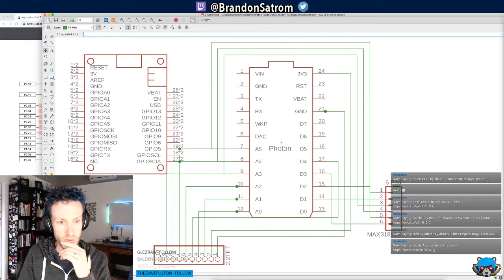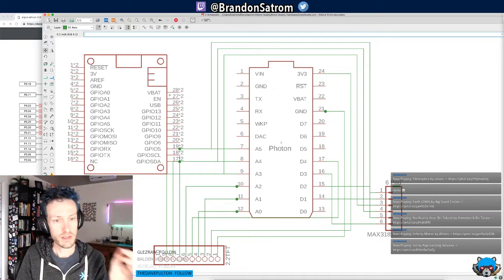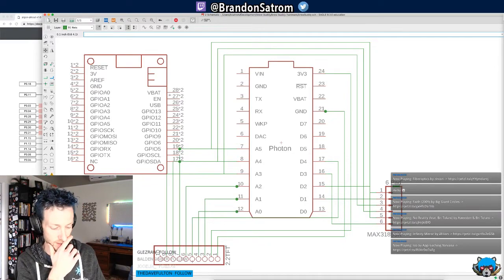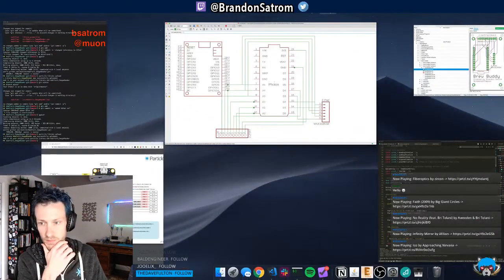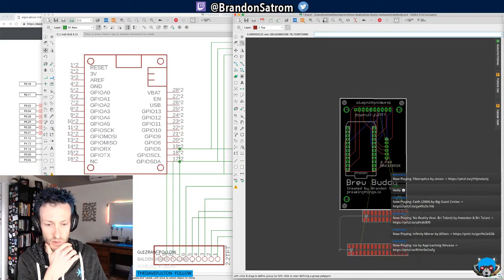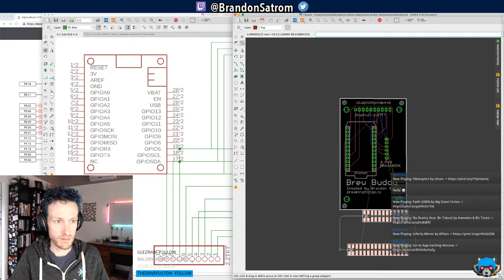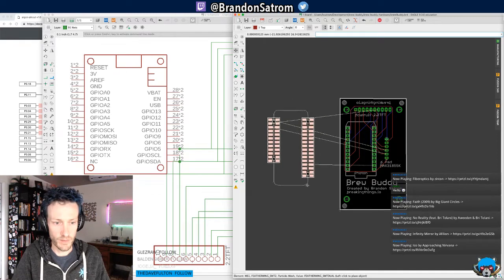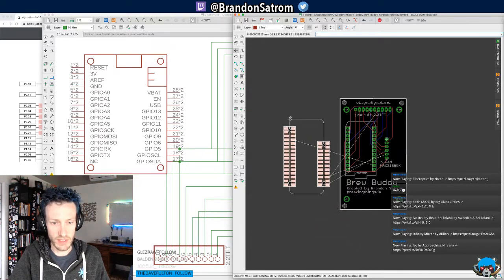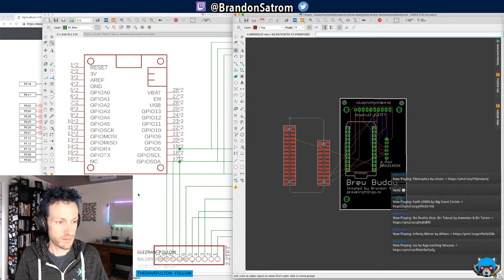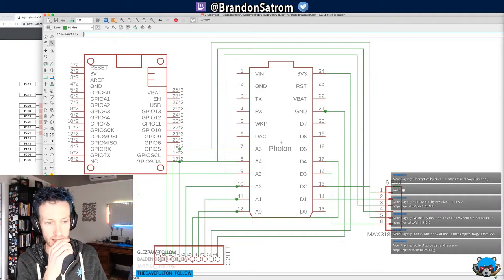All right, and so now it's going to be a matter of just rewiring the right things into the right places, or rerouting things on the schematic side. But you'll notice actually when I update the schematic that I can go over to my board view and this item is here now. The package is actually here. It's been added. Waiting for me to actually put it on the physical dimension layer somewhere. I'm not going to do that yet because I'm going to do the routing. Create my wires properly here. And then I think I'm going to clean all this stuff up.